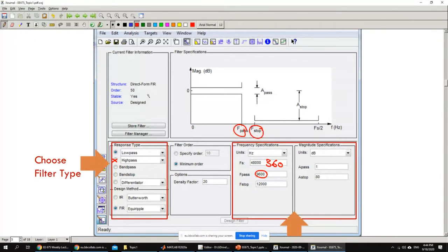Usually, if I wanted a filter that removes 0.5 hertz, basically I want this to be removed. Any frequency below that must be removed. What I should do is probably put f-pass here as 1, and then f-stop as 0.5, and put here the attenuation I want, if you remember. 80 means 1 over 10,000. This is usually very large, right? So you can change that.